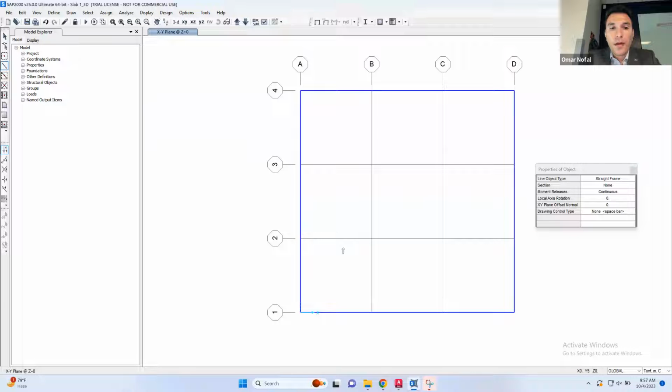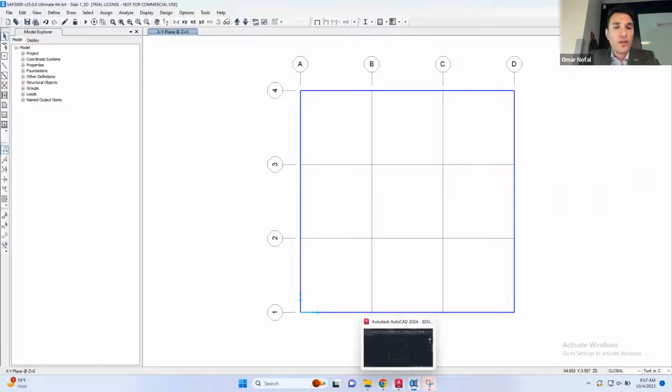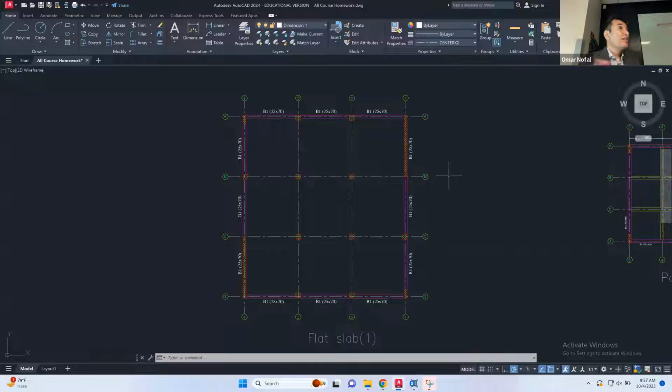and here. By the way, right now I'm trying to draw a 3D model for the structures that we just saw. But let's assume that this is the structure that we started with. Do you guys remember what is the difference between this one and the one that we drew? The one that we did has a column here and column here, not a shear wall. Same thing here. But if I want to model this in my model, all you have to do is select all the joints here and make it hinge. Because this is what the shear wall is doing here.